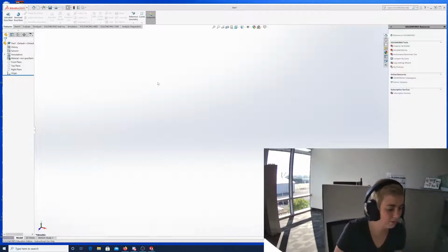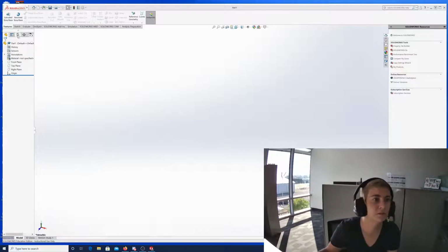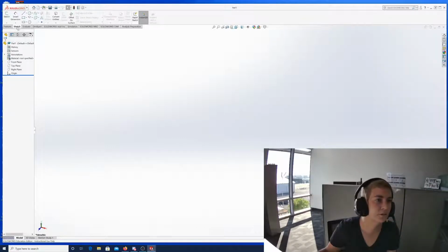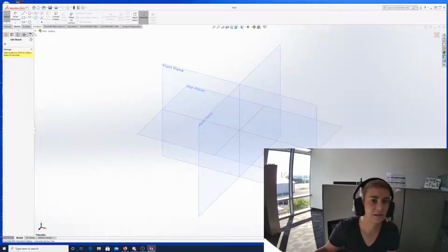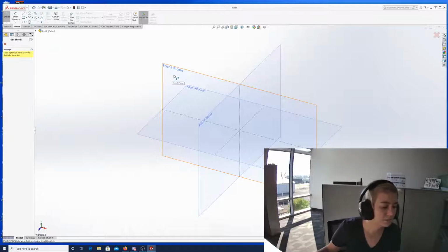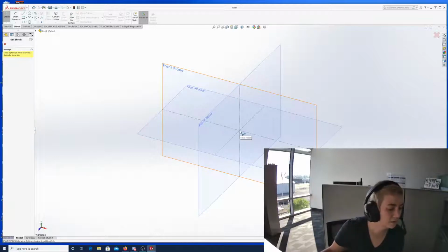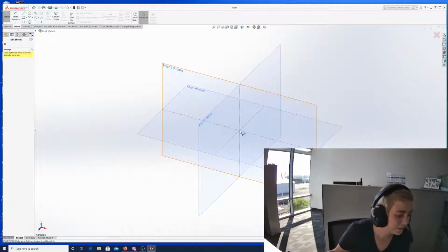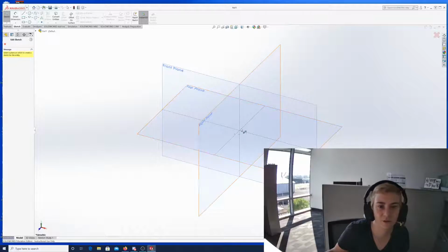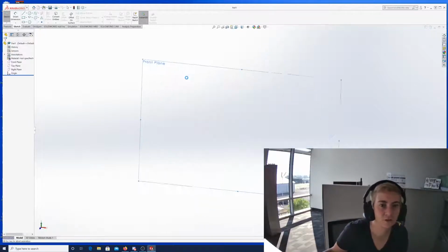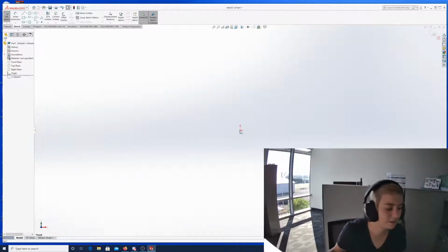And then the first thing, I pointed this out last week, once you start a sketch, you're going to go to the upper left corner and start a sketch. Once you select that, you'll see the origin is where all the planes intersect. So it's basically the center of whatever plane you choose to do your drawing in. It shows it on that page. When you click a plane, you're going to see the origin here.